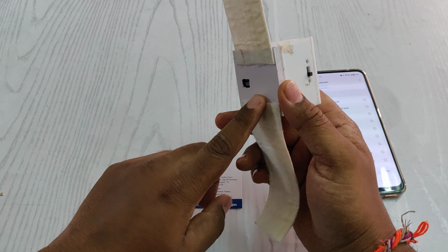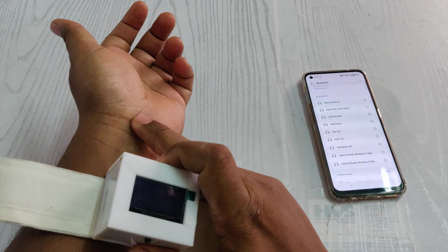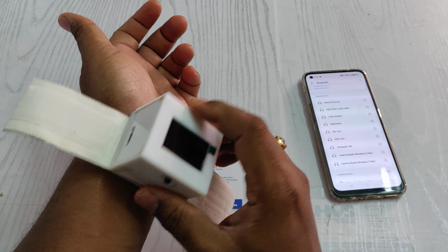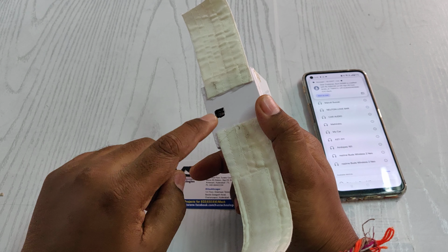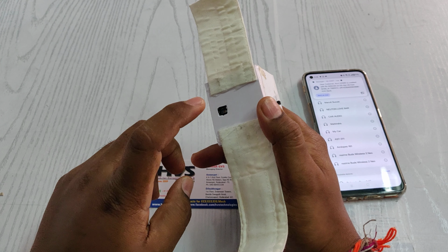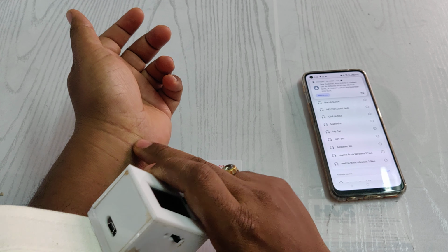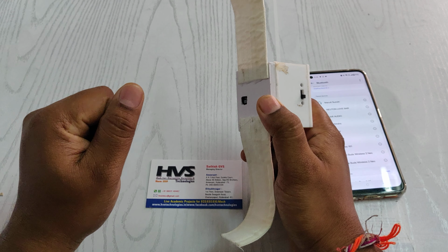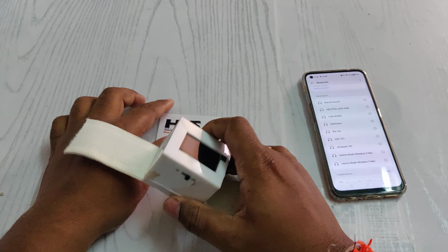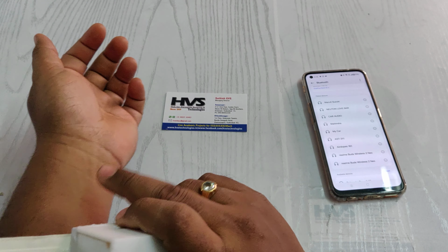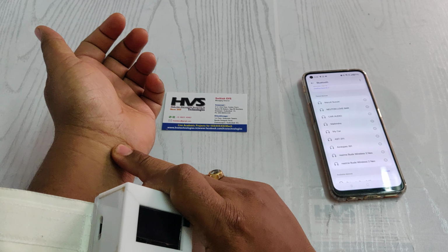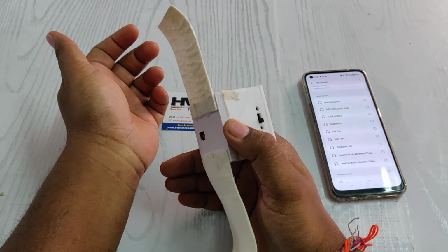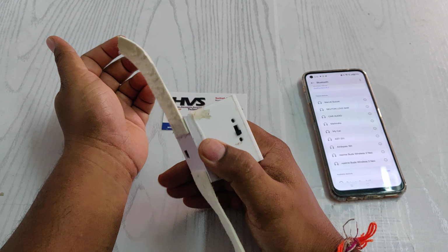When we place this system on the wrist, where the skin thickness is very less, the red LED and IR sensor will first identify the skin surface. After that, the system keeps checking the intensity of the transmitted red LED data. Whenever it is reflected from the red blood cells, we get the reflection, and based on it, it will differentiate the systolic and diastolic.